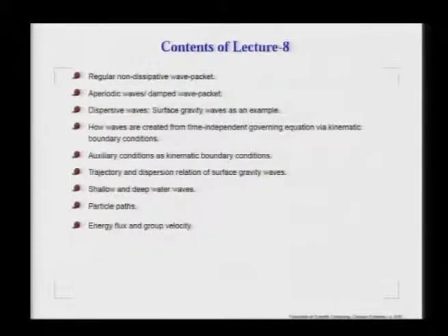We will also notice one particular aspect of this dispersive wave, which is the existence of group velocity. Group velocity is distinct from the phase speed, and it is important because this is the speed at which energy flux is created in the flow.